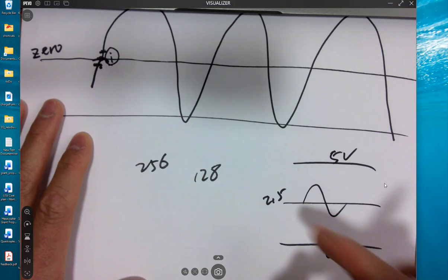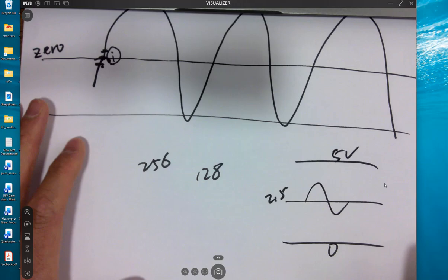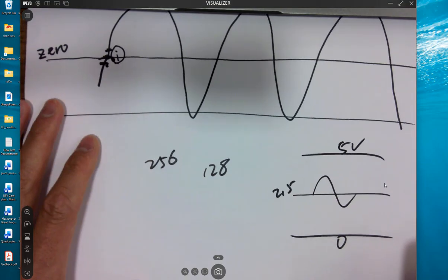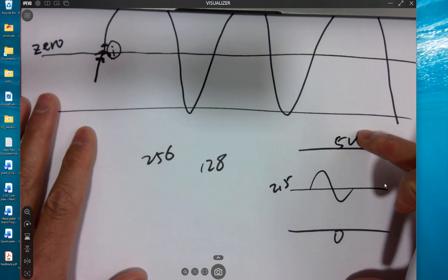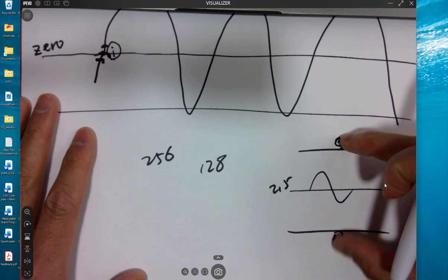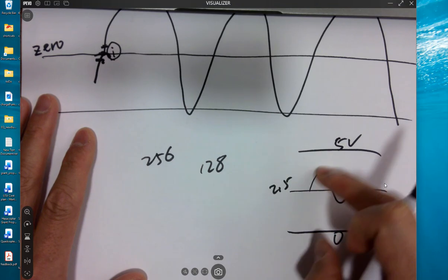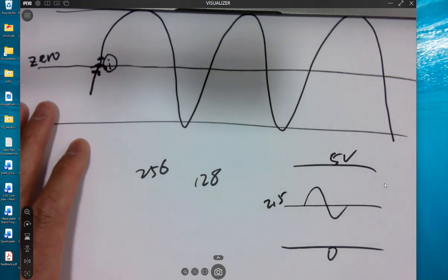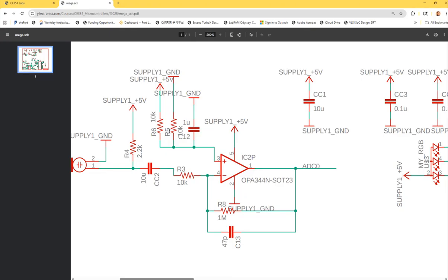How do you lift it? Lift it on the non-inverting terminal by a DC. It's fundamentally the standard way of doing that. Okay, so you don't have a plus and minus dual power supply. It's not 5 and -5. It's only 5 and 0. So I have to add a DC offset to lift it to 2.5 DC, so you can swing your signal around that. That is why we are swinging our input analog signal around that 2.5,